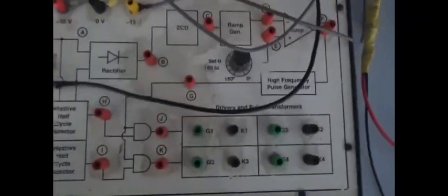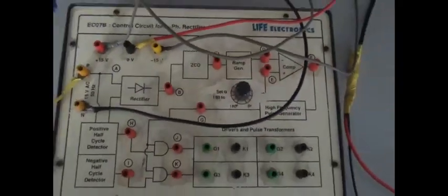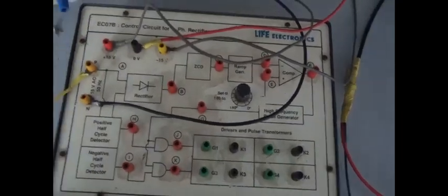And since it is a control circuit, we have many ICs inside this. So to power these ICs, we need to provide a DC supply as well. We are using an RPS here. From plus 15 volts it's given to plus 15 volts in the kit, from common it's given to 0, and from minus 15 volts it's given to minus 15 volts. These are the connections that you are supposed to do for the control circuit.